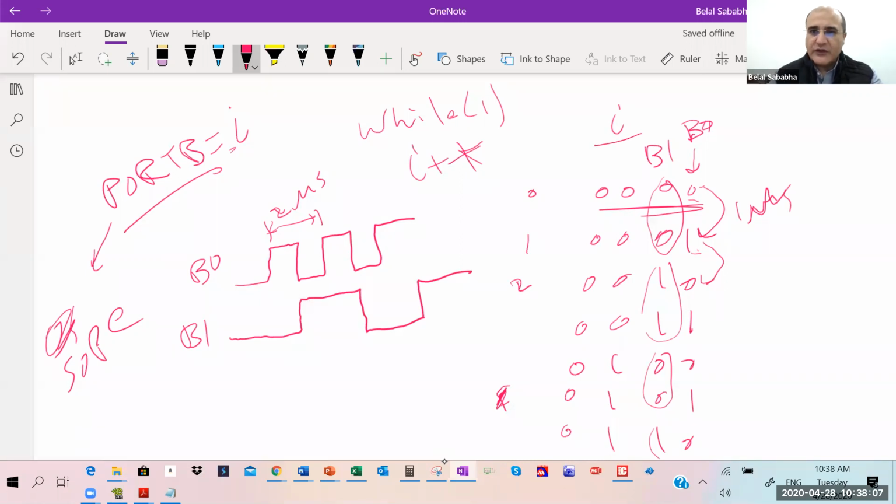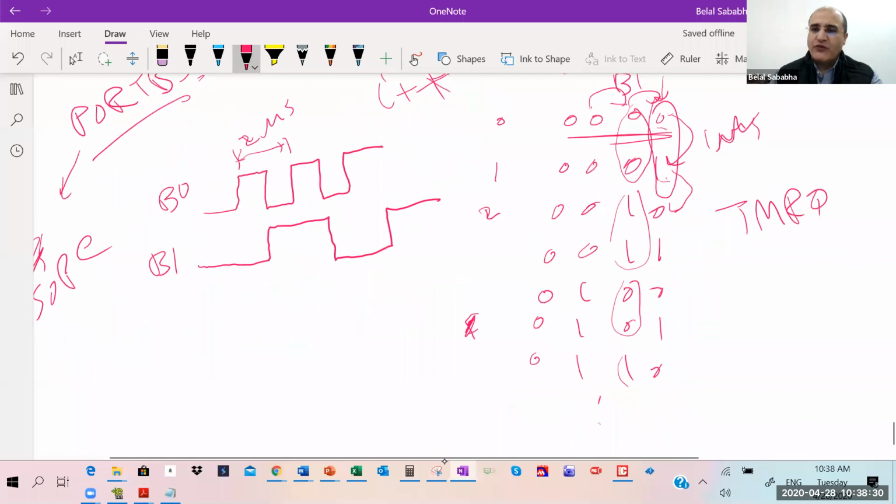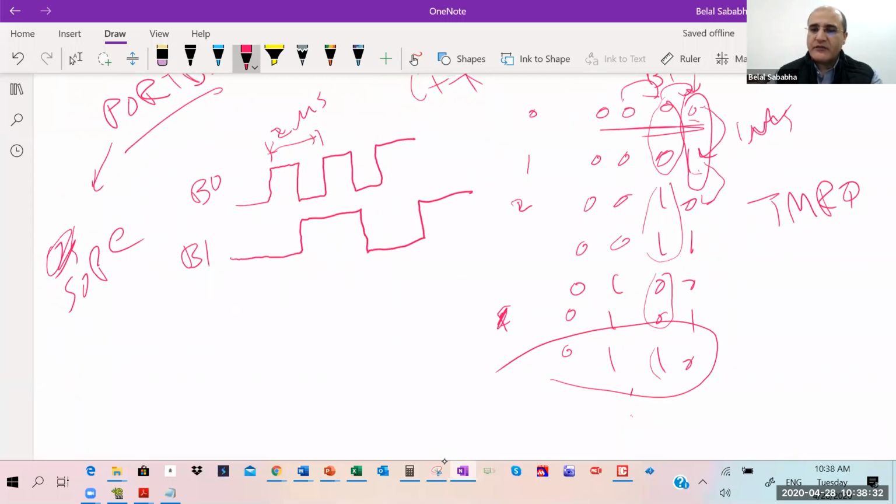So a normal counter, and this applies to timer 0 as well that we started talking about, has the very first bit changing at a frequency half of the frequency of the increment. Then the second bit is half of the bit before it, then the third bit is half the one before it. So a counter is a typical frequency divider system.